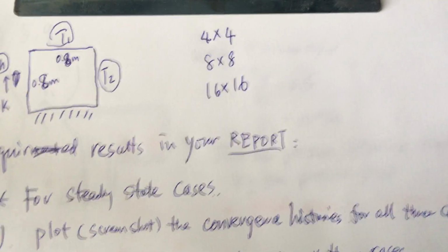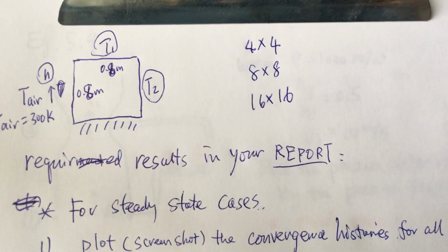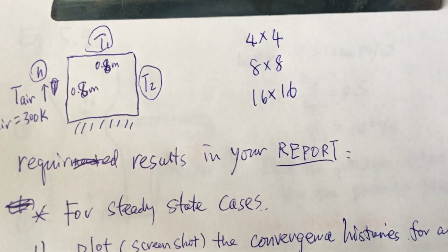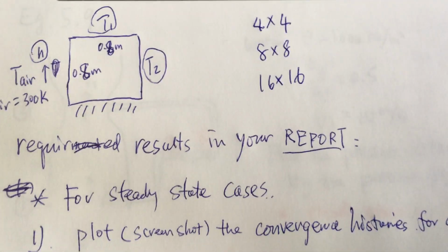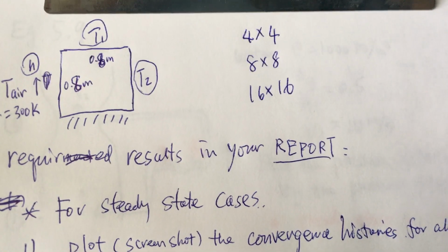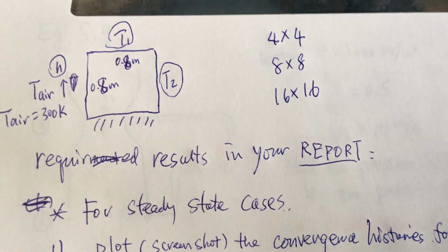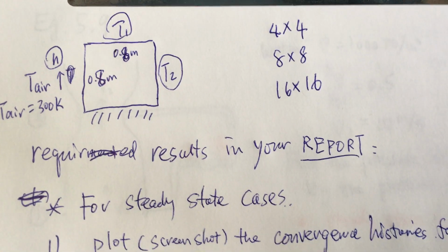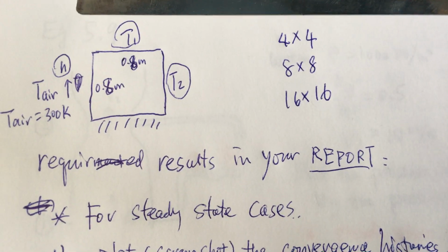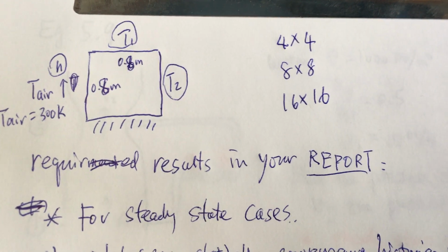That's a residual. Residual means the relative error comparing the current iteration to the previous iteration. When you run the steady state simulation, you need to do iterations, right? You run like 7, 8, and 9 iterations. Every iteration, Fluent compares the entire result in the domain to the previous iteration result.